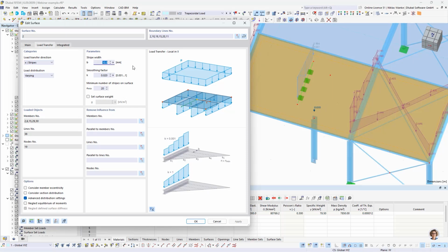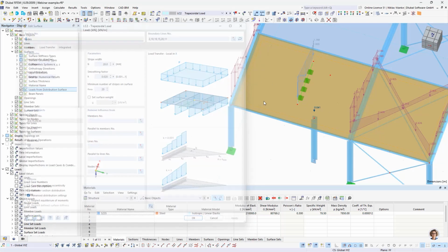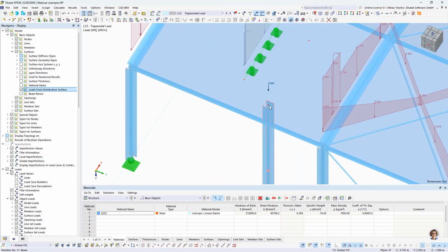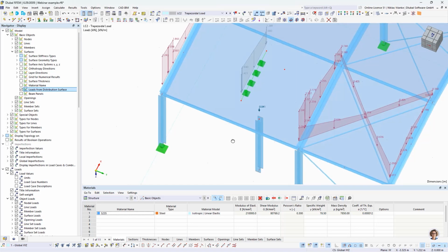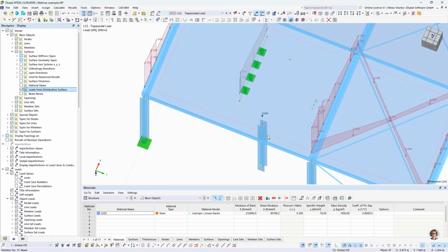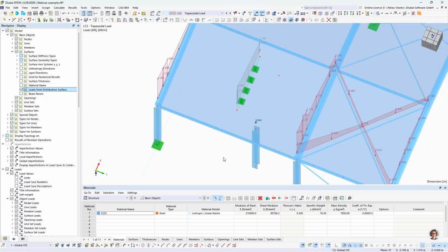And yeah, for example, if I double up the stripe width, we will receive the doubled loading, which is 0.04 now. So that just means that the stripe width has a big influence to the loads on columns in this case. This is why I would recommend to use the isotropic method if you have some structure like this.